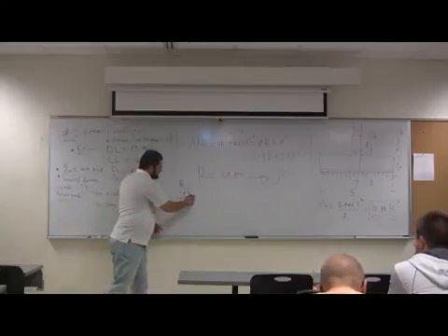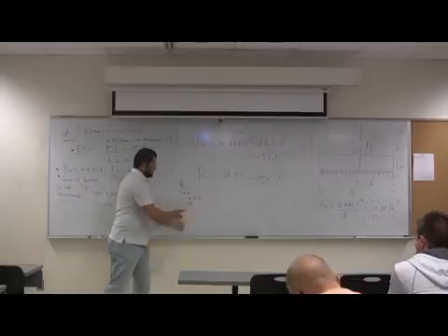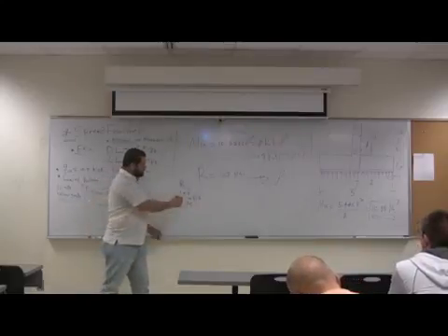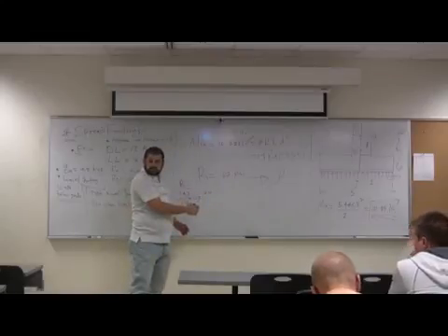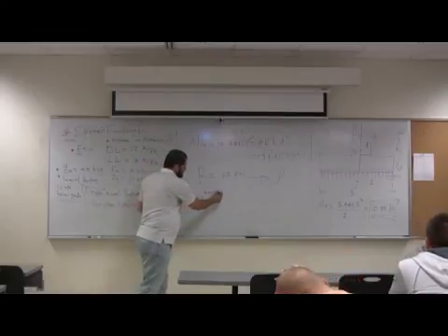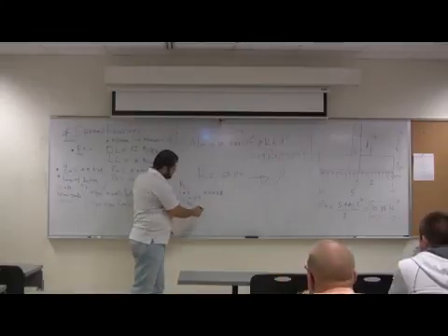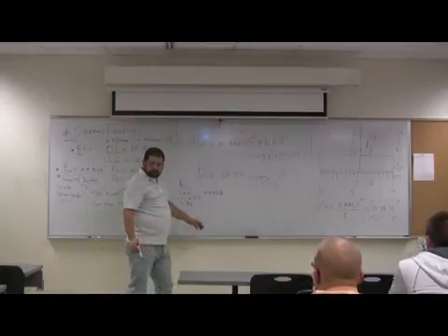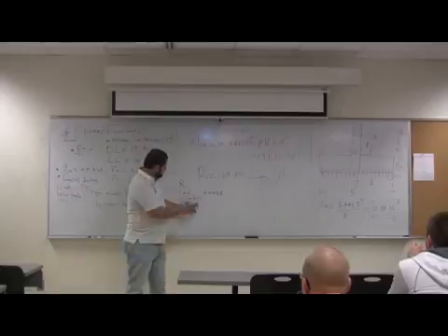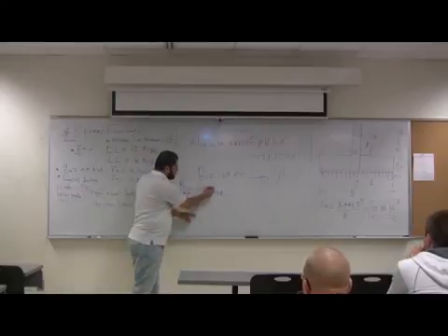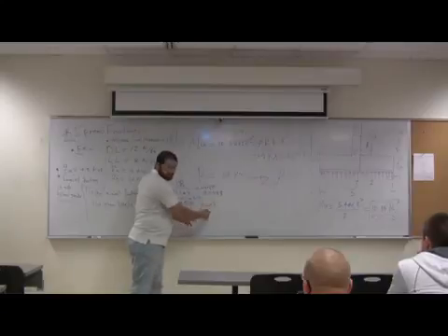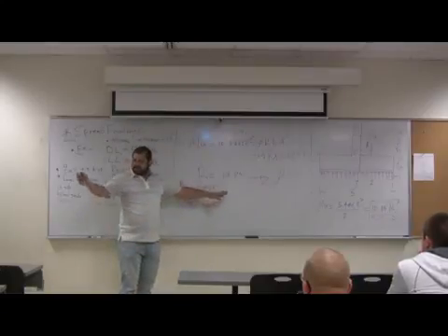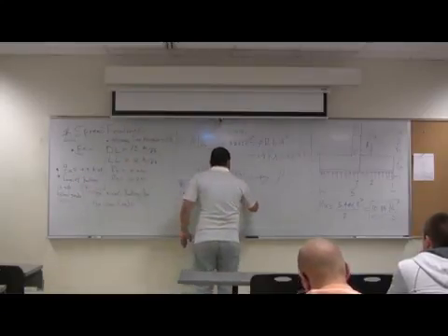So ours is 167. If you interpolate, what is this? 0.0028. That one's 0.0025, and then the other one is 0.003. Both of them are less than rho minimum.